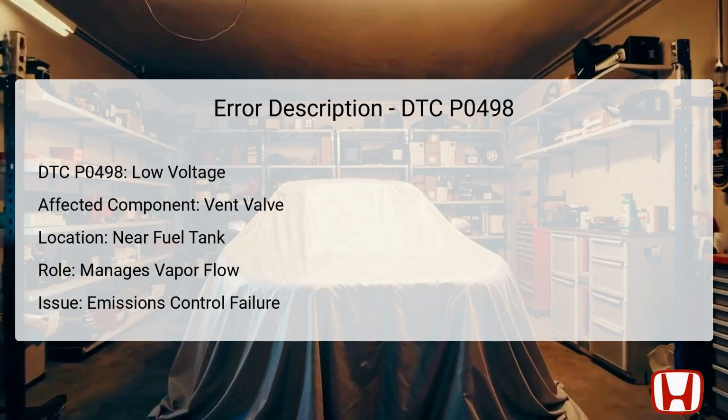The valve is typically situated near the fuel tank, making it essential to access this area during diagnosis. If the electric circuit to this valve experiences low voltage, it may fail to open or close properly, leading to the triggering of this DTC. Furthermore, it's essential to understand the implications of this fault, as it may not only cause a failed emissions test, but could also correlate with performance issues in the vehicle.